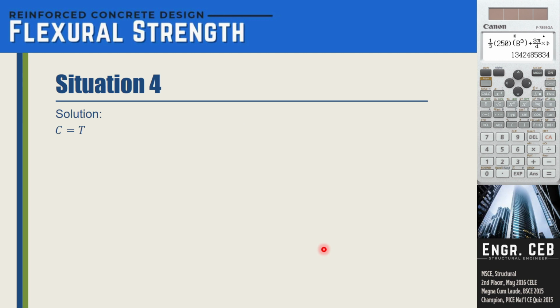We will start with equilibrium because it is important, of course, that the compressive force created by the combined concrete and compression steel is equal to the force provided by the tension steel. So that is 0.85 fc prime ab. This is still our earlier expression, force in concrete.